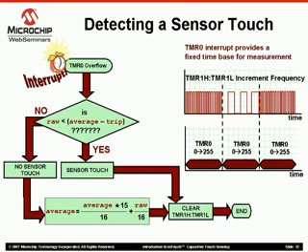If a sensor touch has not occurred, the current value in timer 1 registers is averaged into the 16-point running average. The timer 1 registers are always cleared at the end of every timer 0 interrupt routine, and the CPU returns to whatever it was doing prior to the interrupt. This completes the basic system.